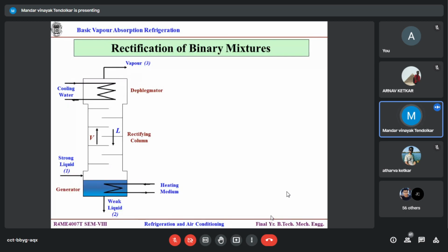on at every plate. That is why those are the perforated plates, and those are stacked in the alternate manner, so that vapor will flow in any random manner because it is free to flow the way it wants, and the liquid starts dripping down through the perforated plate because it is at higher density, obviously. We do not put it as a cup, otherwise it will stay there. I want the liquid at the bottom, so we put it as a perforated one. So under the higher density and gravity, both effect cumulatively, liquid will fall down.